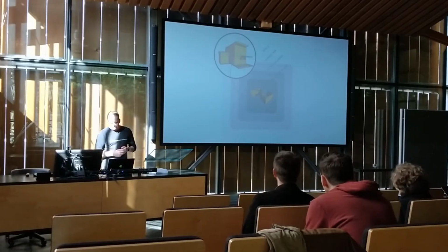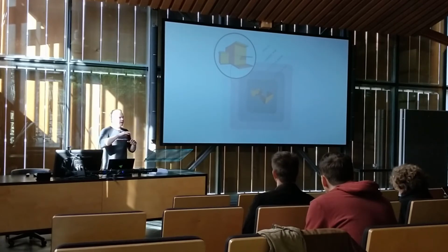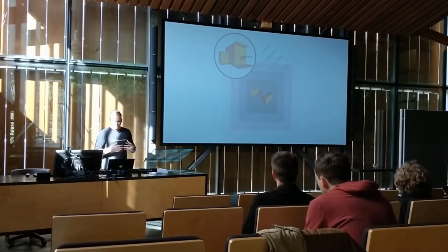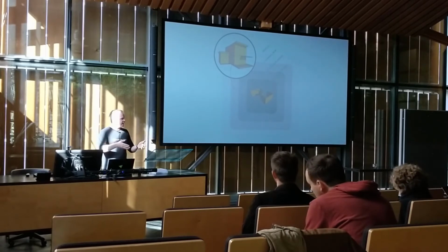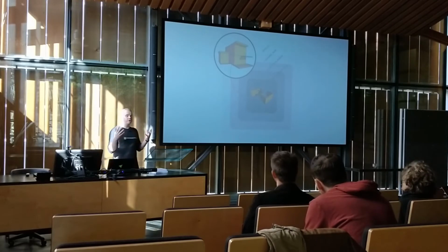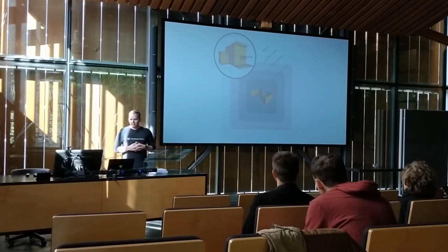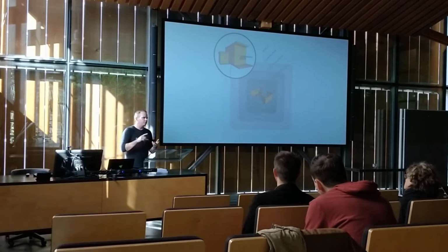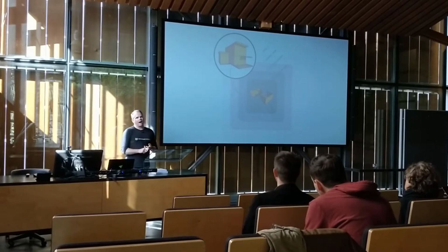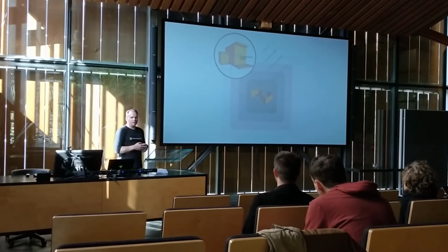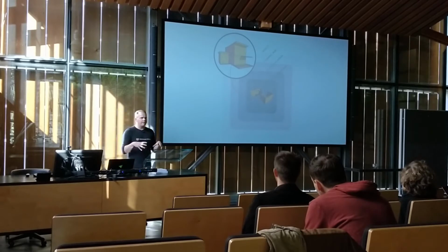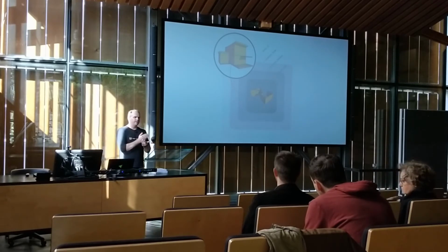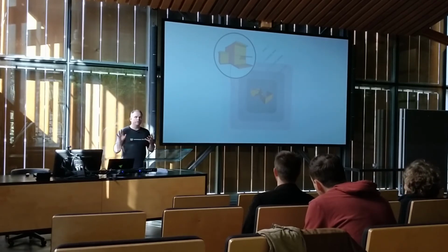The reason we're doing that is to fully control the model. We can break it apart by levels, we can break it apart by interior and exterior and peel away the skin so we can see inside. We can keep it lightweight when we're working on just the outside, and turn off all the stuff on the inside. We can also create demolition plans and control line weights. It can get more complicated. You can add all kinds of stuff in here and make Condoc automate phases, option A, B, and C, and wall type 1, 2, and 3. I explained that in the book, but this is the baseline system that works every single time for every single project, whether it's a 10-story renovation or a 1-story new construction.